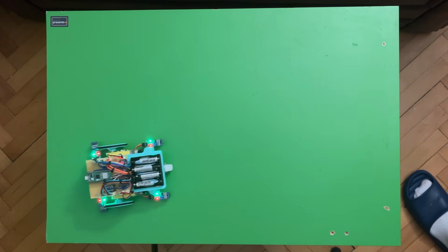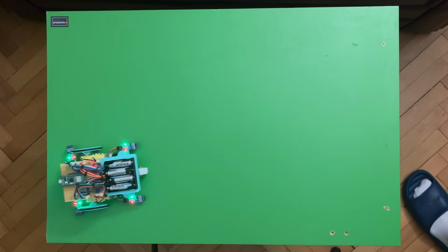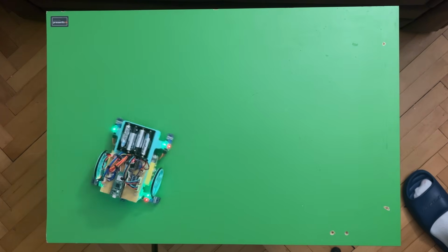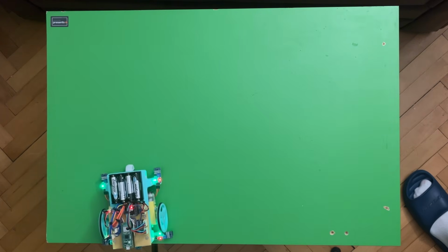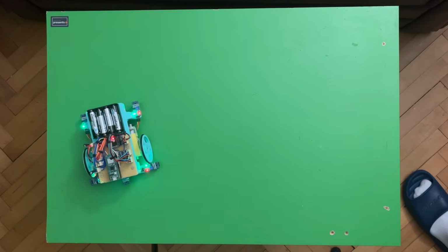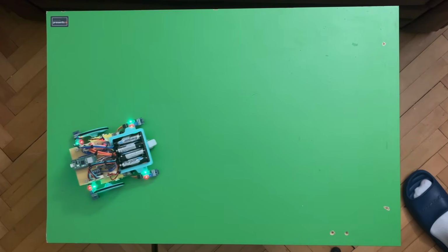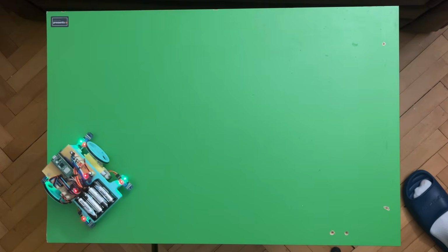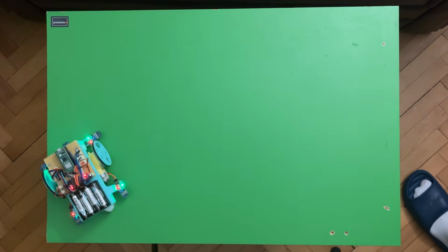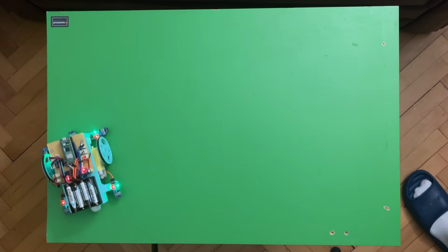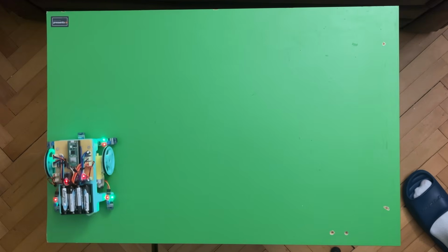This is the 100 millimeter move, so how far away one stripe is from each other. And you can see there is a bit of skew, and that's because these sensors are not ideal, since the wheels are slipping as the robot is moving around and so on. Ideally, we would have more sensors, for example, a LiDAR or something like that, to properly drive this robot and do sensor fusion, but that's a topic for another video.